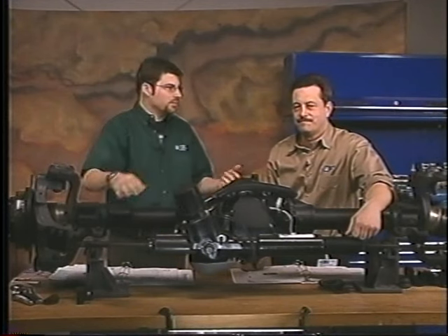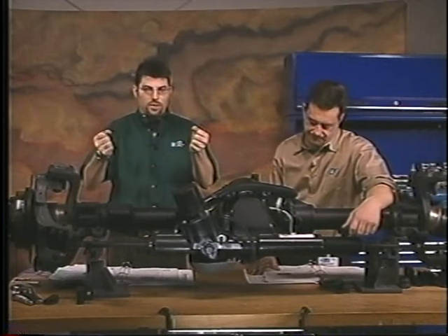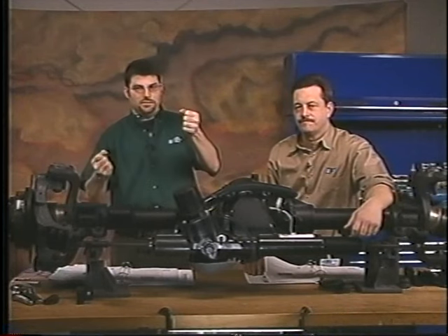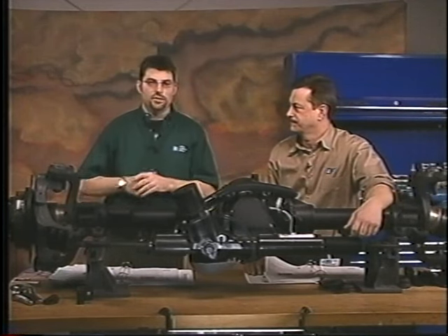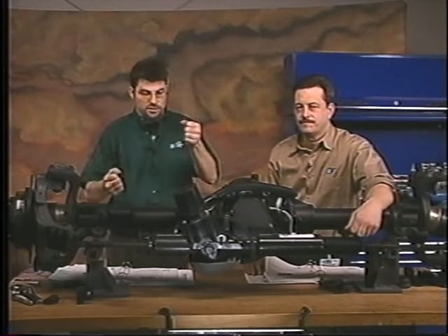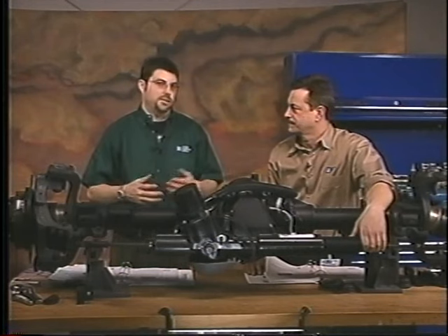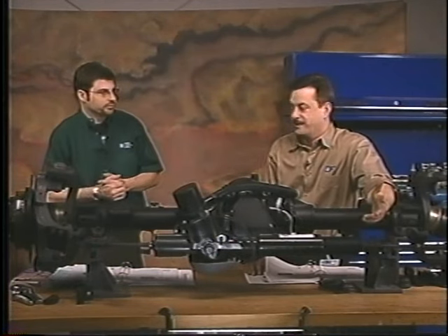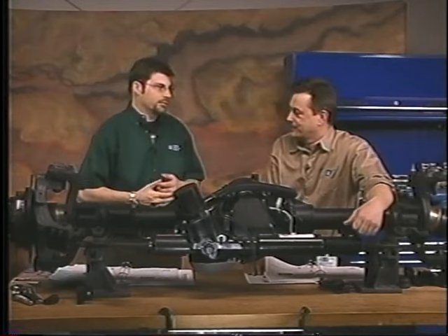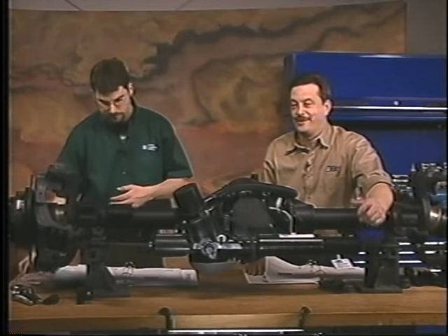Now, basically what Delphi Engineering is telling us is that when we're in the four-wheel steer tow mode, we may see our steering wheel offset slightly. They're telling us plus or minus 5 degrees. So that's definitely an important point that you want to remember. Plus or minus 5 degrees may be off, it may not, but you should be aware of it in case you get a customer who comes in and thinks they have an alignment issue. If it only happens in four-wheel steer, it's not a problem. Don't sweat it. And 5 degrees is so small. They're paying far too much attention to the steering wheel, not near enough attention to the road.